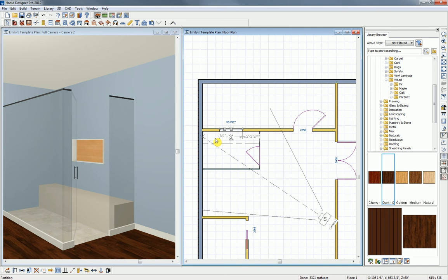Now let's talk about the wall covering. We need tile around instead of just our walls. So instead of selecting the whole wall and changing the wall covering on the entire wall, we just need different portions. That's what this break wall tool is all about. Select the break wall tool, single click on the wall, and all the intersections that you need. And then we can single click on that portion and just change that portion. I'm going to just hold down my control key again to multi-select.